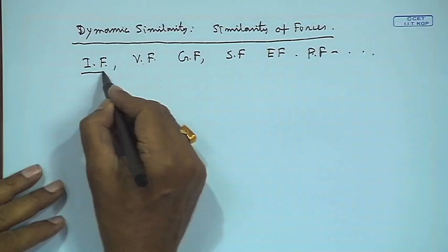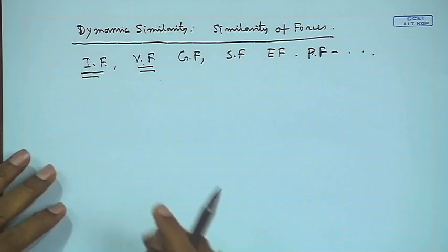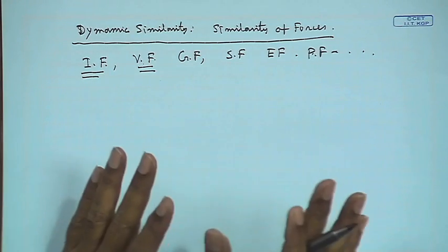to be same. So, to make this, we have to find out the parameters that define the inertia force and viscous force. Now, here we know the ratios of velocities we get in terms of the velocities, but when we say that the ratio of inertia force by viscous force has to be same for both the systems, then we have to know that the ratio of inertia to viscous force is given by which parameters, which variables of the fluid flow.